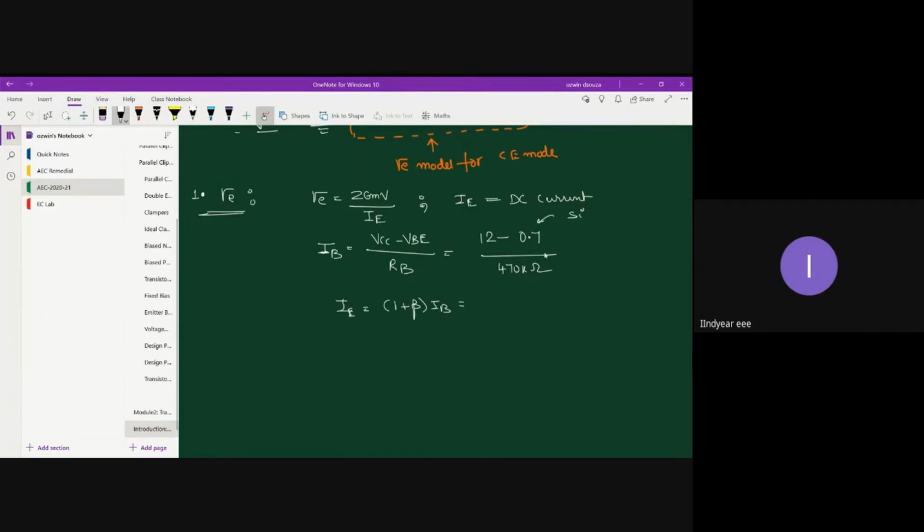Here I want to make a point. If given, you take the respective transistor, whether it is silicon or germanium. If not given, always assume silicon transistor. Don't become aggressive and don't take germanium or gallium arsenide, because in the scheme, almost all the times they will take the VBE potential as 0.7. So please take it as silicon if the type of material is not mentioned.